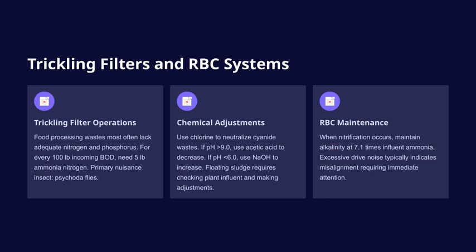When nitrification is happening, it's vital to maintain alkalinity at about 7.1 times the influent ammonia levels. This helps ensure efficient nitrification. Also, if you hear excessive drive noise, that's often a sign of misalignment, which should be addressed immediately to prevent damage or process disruption. Throughout all this, it's clear that proper operation and maintenance are key to effective treatment, supporting the overall goal of sustainable and efficient wastewater management.